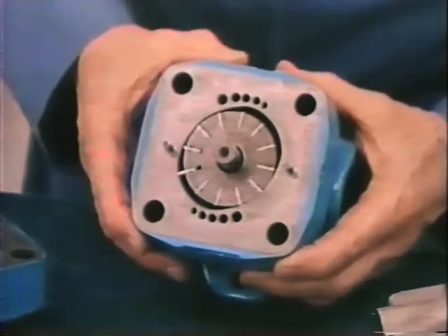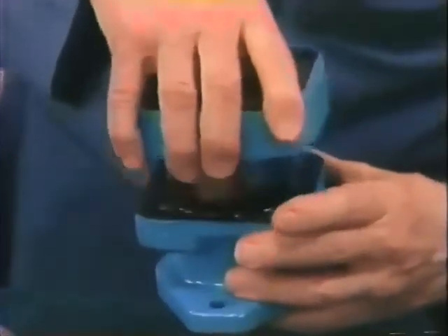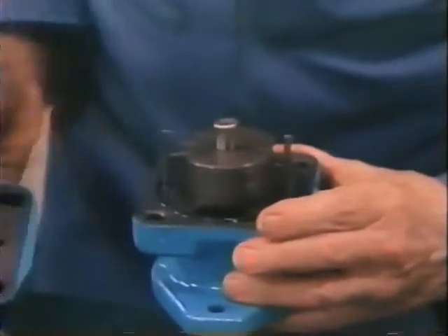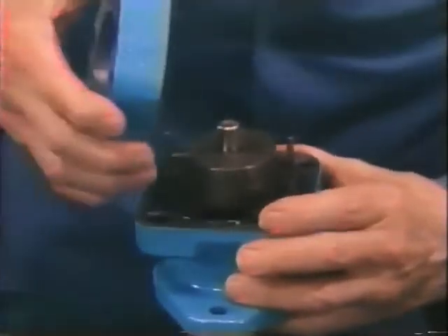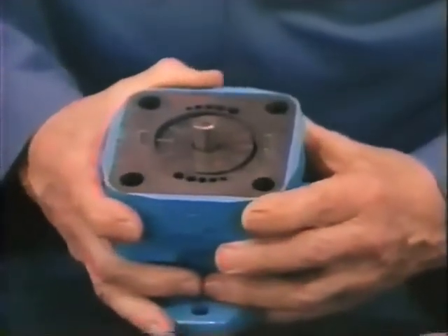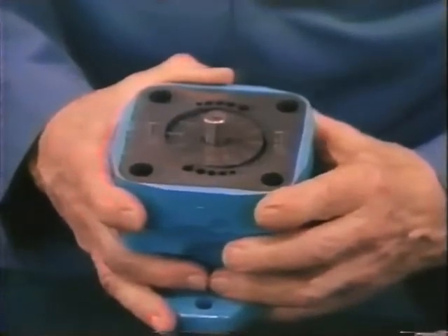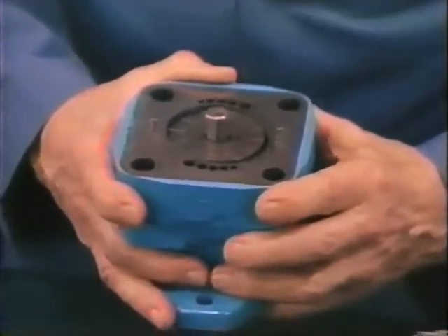Pump rotation is established by the position of the cam ring. Removing the ring from the locating pins and replacing it with the opposite side facing the pump body automatically rotates the cam 90 degrees, and the pump may be driven in the opposite direction. Arrows on the ring indicate proper rotation.